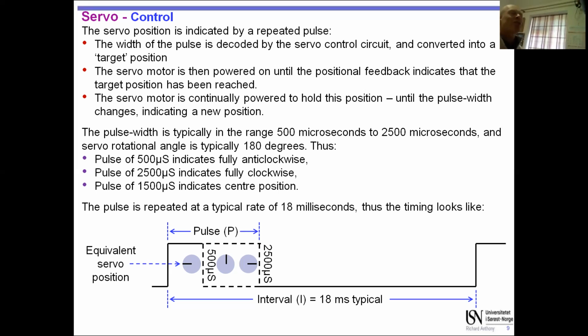And sometimes in designs, this is where engineers can get confused. Someone draws a diagram looking from the top, someone else interprets that diagram looking from the bottom, and the servo goes the wrong way in the final product, things like that. So coming back to your coursework, this emphasizes, not just for servos, but for anything, how important it is that your documentation is clear. This is an example where I've personally made mistakes and confused myself, and I've designed it perfectly, and then the servo in the product goes the wrong way, and you have to rebuild certain bits of your code. It can be quite annoying.